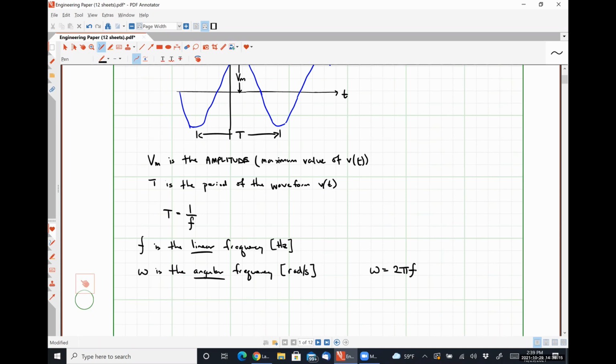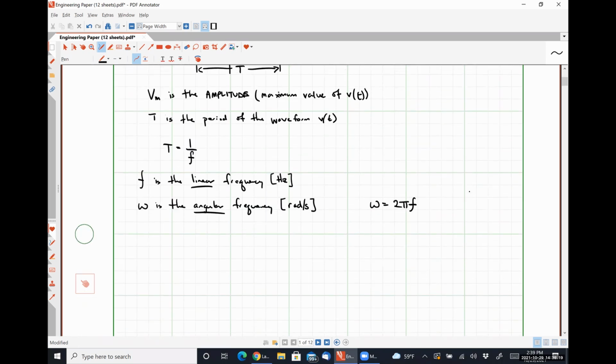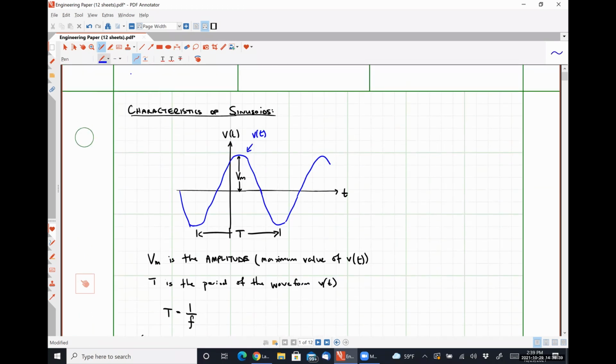And the last thing we have is what's called a phase angle, right? So phi is the phase angle of the waveform. So before we talk about what that is, I'm going to better mathematically define what our voltage waveform is here, okay? So we'll have some magnitude Vm cosine omega t, which represents how quickly that signal oscillates as time progresses, plus some phase angle phi, okay? So phi represents how far to the left or right we have shifted this waveform in time.